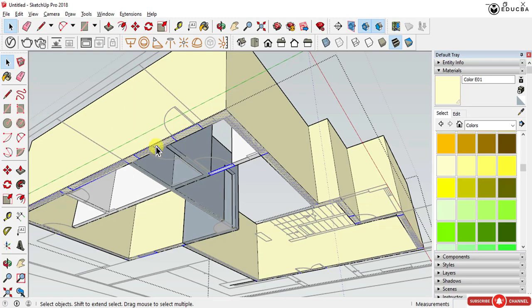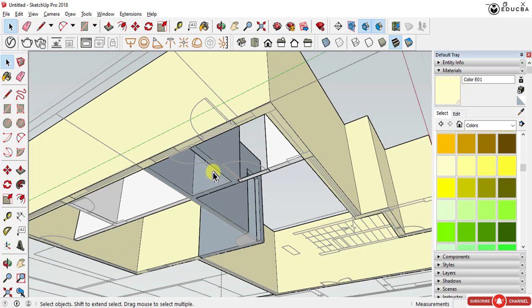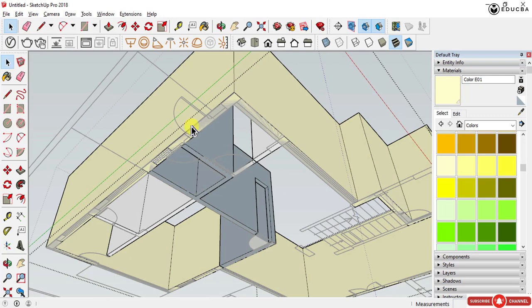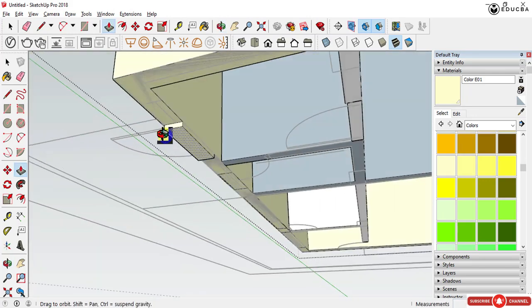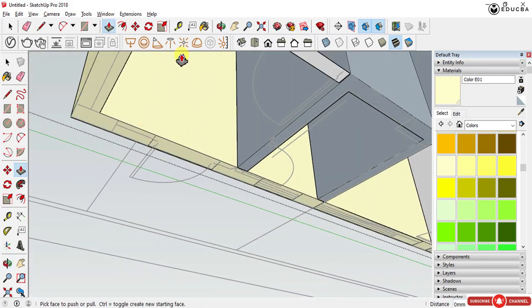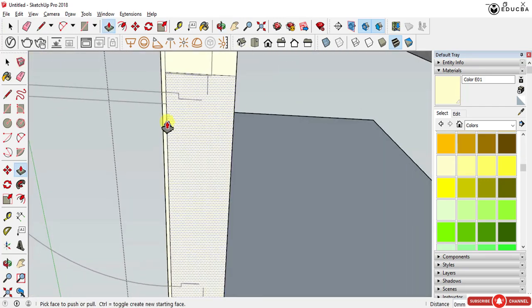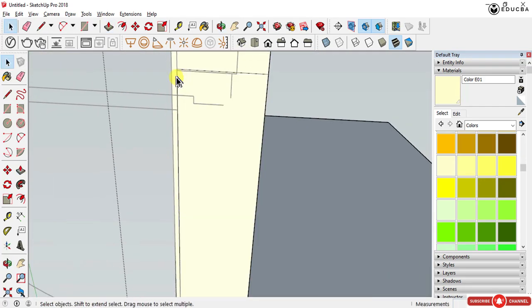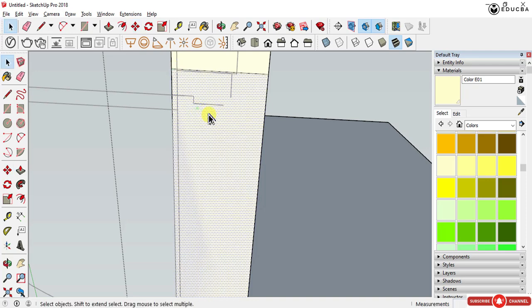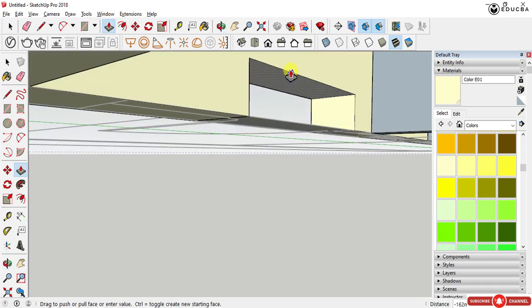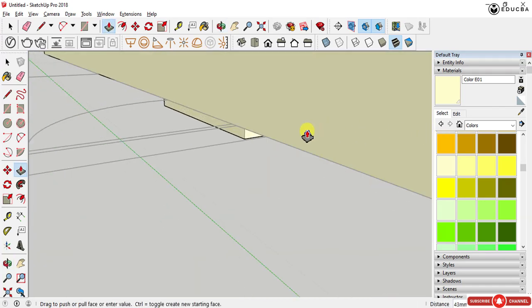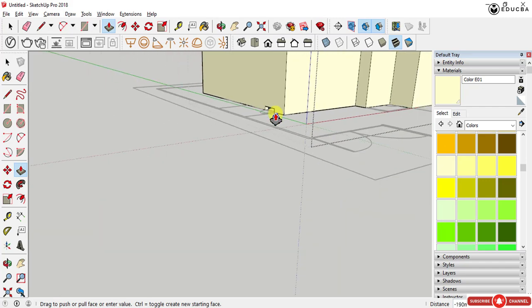You can see the surface has been pasted and we have different planes at every particular level. Now we can push or pull the surface we want like this. If you can see, in this case, it looks like the line is not complete. We are going to move this particular line, the move command, and see now. If we push, it gets on both the surfaces. So it is very necessary to cut through a surface. You need to have both the surfaces joined together with the same plane.